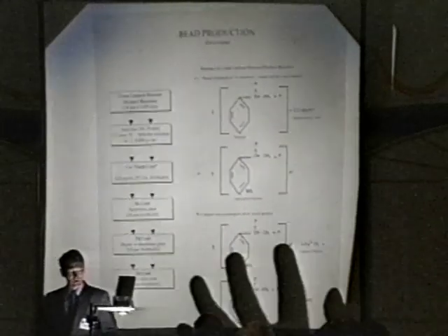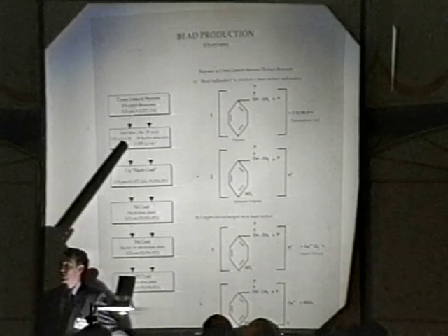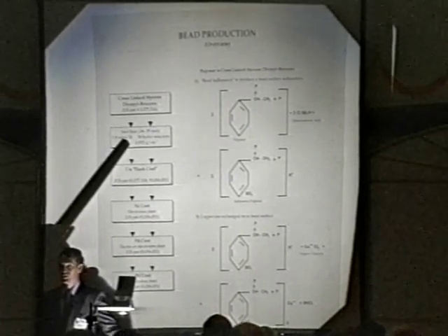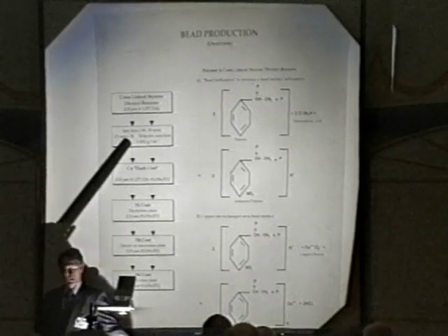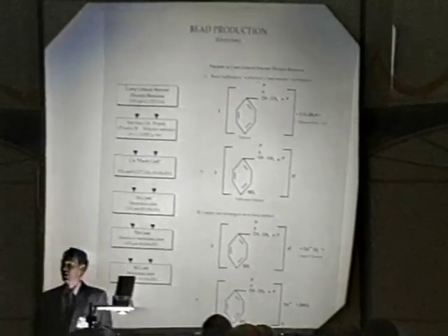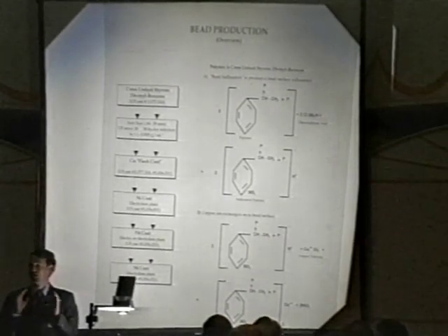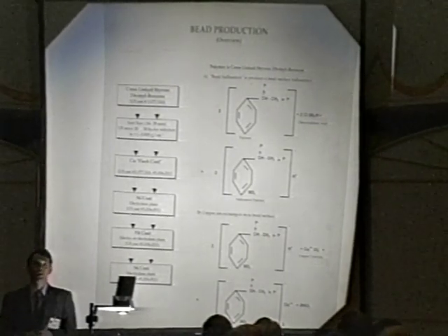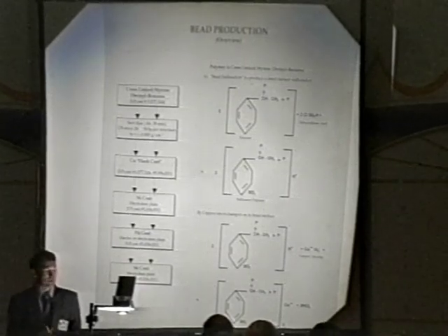The beads themselves are made first by sorting to a precise size through a sieve system and then hydroselecting, similar to chromatography. They are then sulfonated on the outer coating, which makes it charge carrying. They're dipped in copper chloride, which gives it a flash of copper.